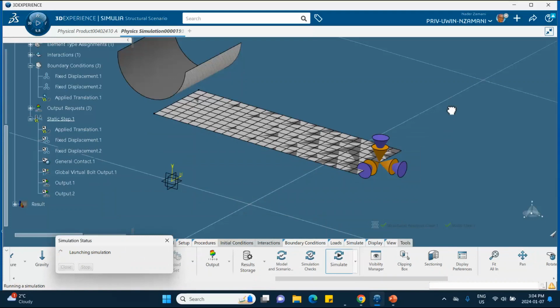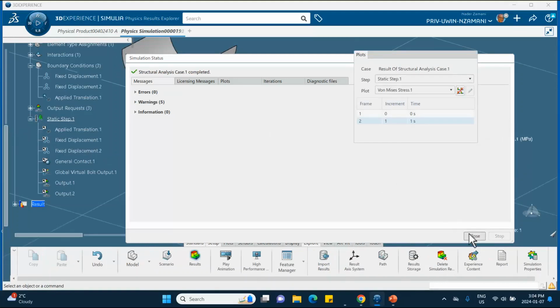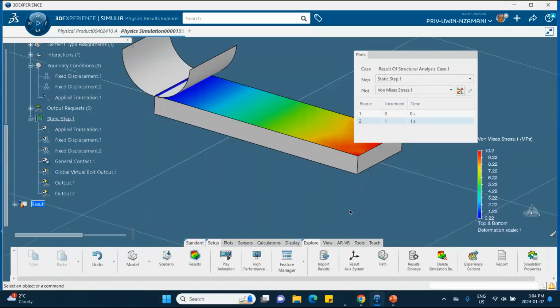Because to say that that is the bottom surface means the top surface is created by going 10 millimeter up. As soon as you go 10 millimeter up, it touches the punch, and as soon as the punch starts moving, the contact is already there. So a motion of 0.1 millimeter will develop stresses in the beam right there.